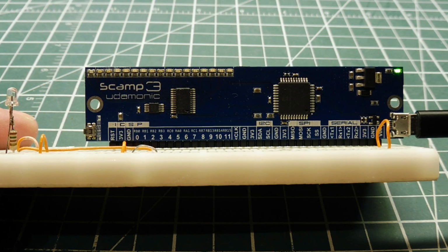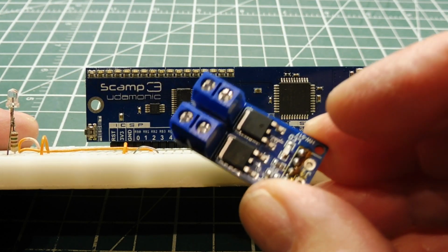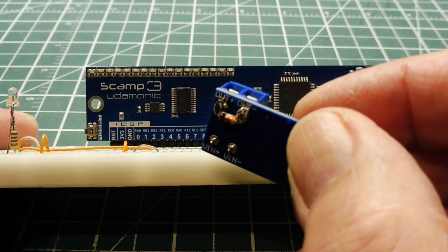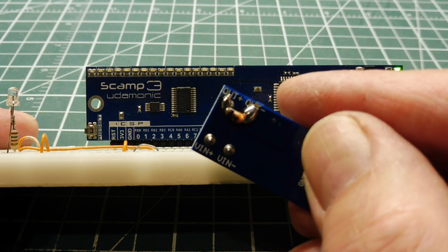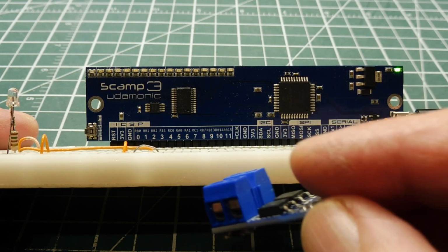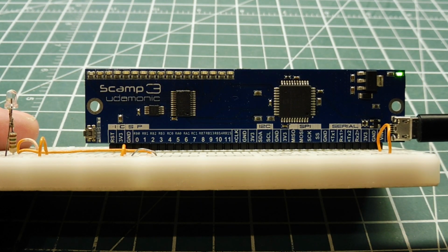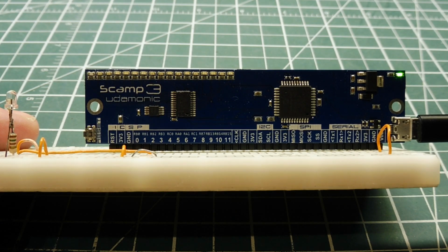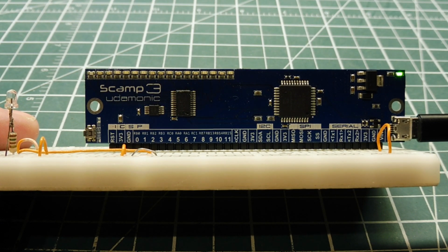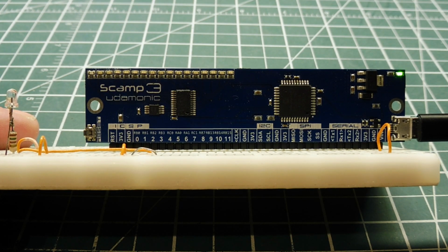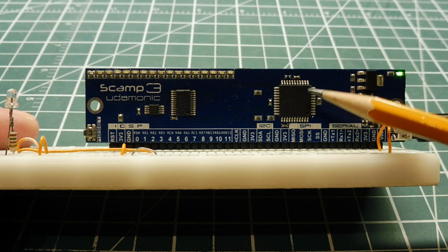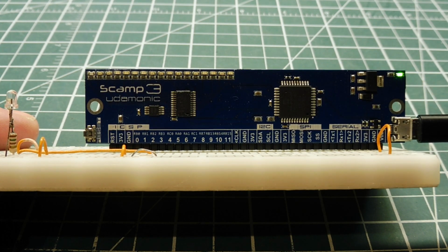Okay, so that was my little tutorial on how to get PWM going on the Scamp3 board. So all you need is some kind of MOSFET driver, like this one here. And I did add a freewheeling diode onto the output connector for inductive loads. Now there's 6 PWM channels on the microcontroller, and you can get them all up and running at the same time, and it's not taking any resources out of the microcontroller. So this is very handy for robotic applications, and everything is on board the chip. It's running FlashForth and has support for PWM, so it makes coding very simple.